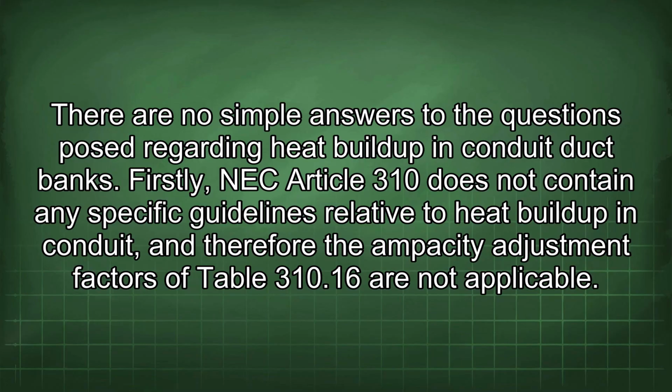There are no simple answers to the questions posed regarding heat buildup in conduit duct banks. Firstly, NEC Article 310 does not contain any specific guidelines relative to heat buildup in conduit, and therefore the ampacity adjustment factors of Table 310.16 are not applicable.